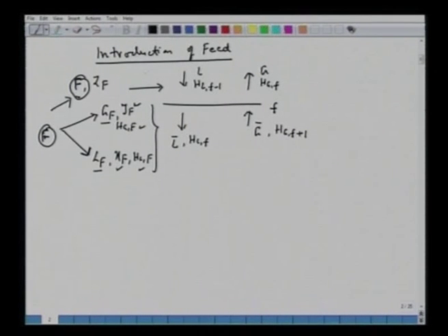All right. So what we do now is the balance. So F plus L plus G bar. So F, L, G bar arriving at this plate F will be same as L bar plus G, the two streams leaving this stage. Right. In McCabe-Thiele method, we said that energy balance is not required, but this is the only place where one has to make this energy balance, enthalpy balance. Right, just like we did in case of Ponchon-Savarit methods.